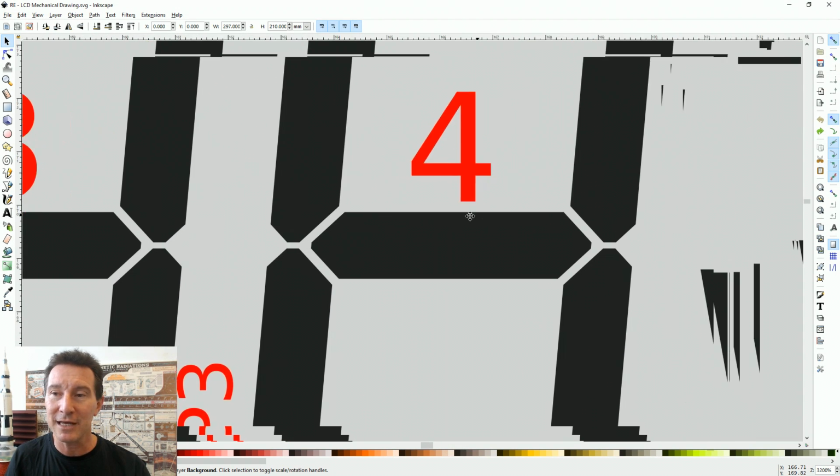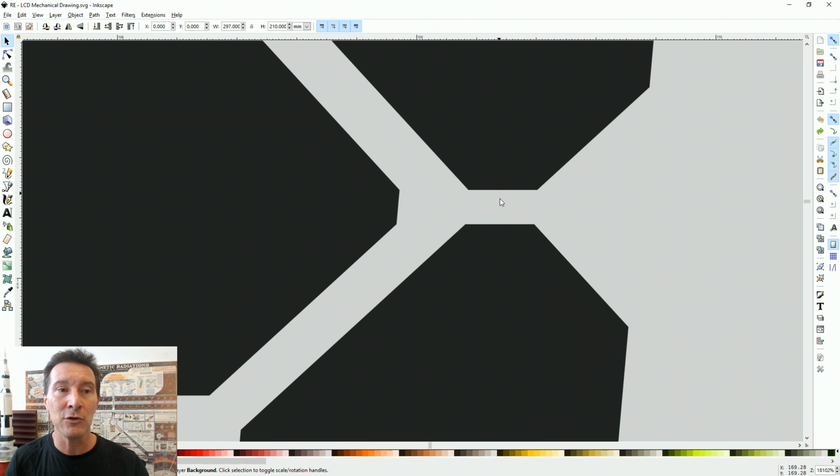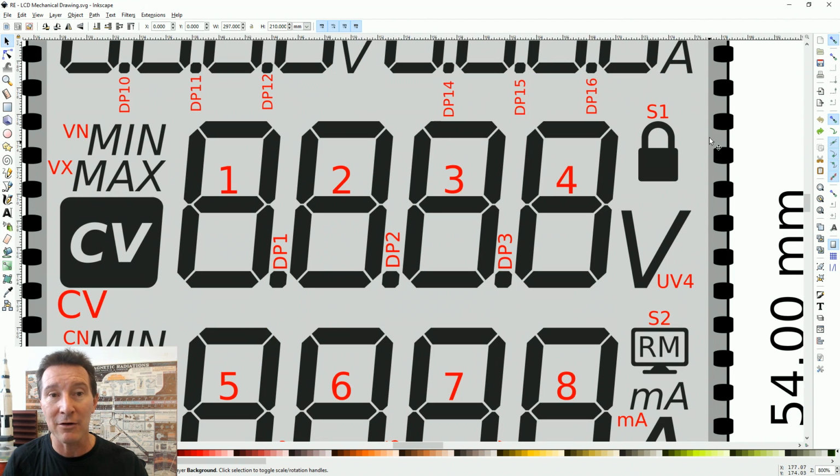just remember, when you're actually getting these manufactured, this segment in here, for example, you have to allow enough gap in between, not only to route that trace out to ensure that it doesn't touch the others, that conductive trace from this inner one, but then you've got to allow the clearance as well. So that's why we said before, typical spacing and trace width might be 0.1 millimeters and 0.1 millimeters. So that total in there would have to be 0.3 millimeters if you wanted to squeeze through a 0.1 millimeter conductive trace. And then you've got to, of course, route it out to a particular pin.